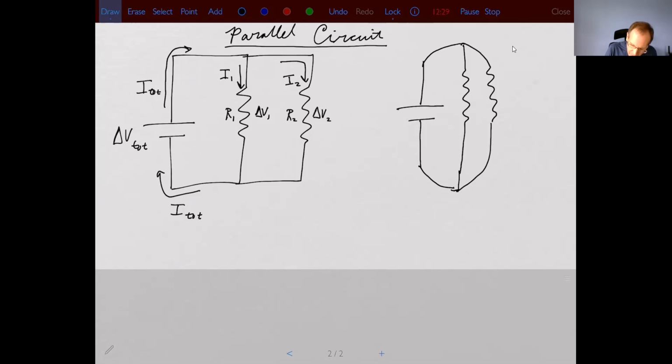And again, I can think about it in terms of potentials. If this is the potential on this side of the battery, say V1, because this is just a wire, right? These are all just wires. There's no voltage drop across the wire. We're assuming it has very low resistance. So this is also V1, and this is also V1. They're all at the same potential, is what we say.